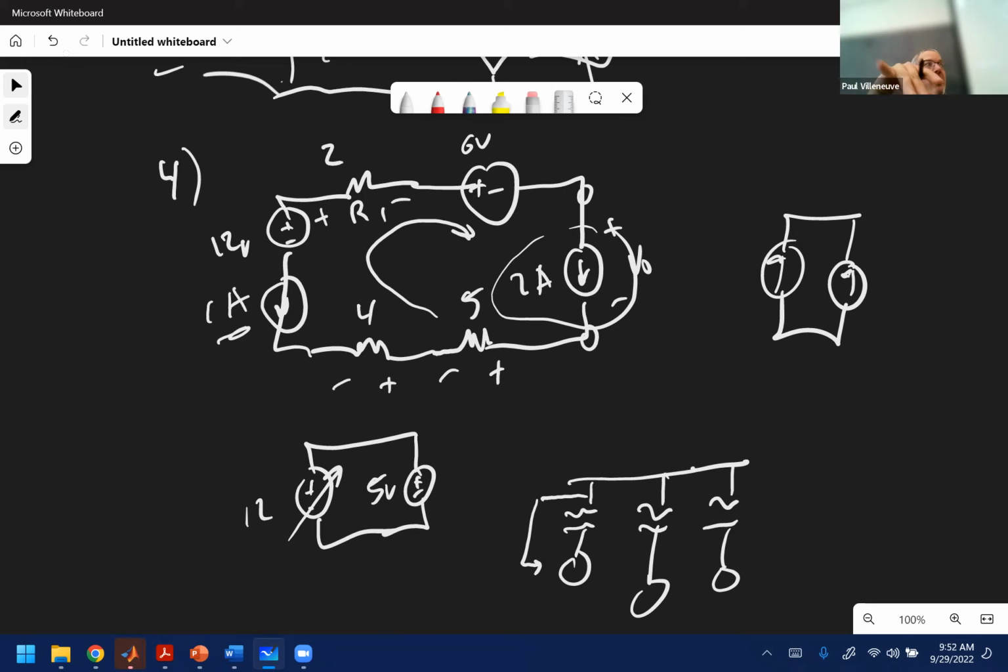Usually you have very large generators like nuclear power plants that are so much bigger than anybody else that they can really control the frequency. In Millstone Unit 3, they have a 1500 MVA generator, and there's no other generator in New England that big. So if I have a generator down the street that's 200 MVA, it can't force Millstone to move off its voltage. So that's why really big generators usually are really good, as long as they're well maintained and operated. Those set the voltage and frequency, and then everybody else has to adjust themselves to that. People have known this for years, but we just deal with it.